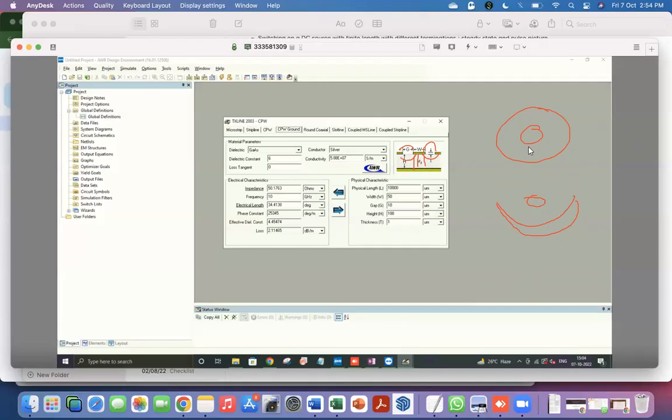Especially if one includes a certain feature, which I forget if I mentioned, the idea of vias, that in a CPW, the two ground planes on either side have to be at the same potential. And this is not something that's going to happen automatically.